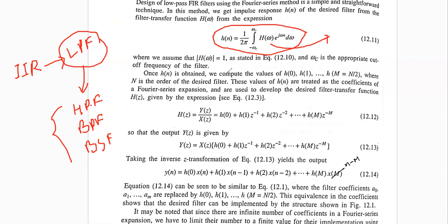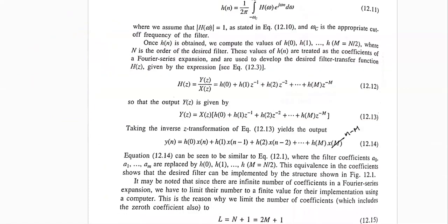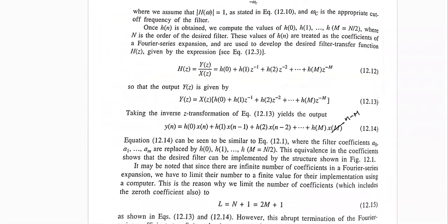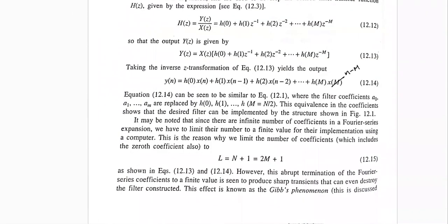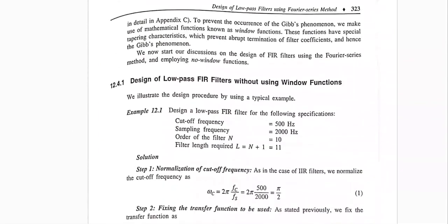However, in case of FIR type, you can't do it. You need to do it one by one. You need to implement that individually for the low pass filter, high pass filter, band pass filter, and band stop filter. So that is also a fundamental difference between FIR and IIR filter. Okay, so here by definition, what is the order of the filter and how we can implement those things, we'll talk about with an example that will give us a clear idea.